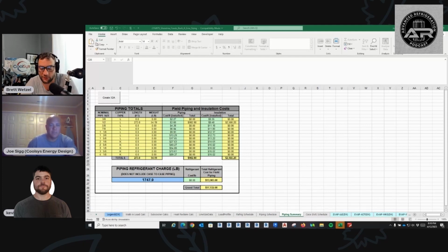All right, so one more time, you take the amount of case piping volume of refrigerant, that volume of CO2, and then you multiply that number by 1/4, because we're not using the flash tank as a full pump down device. We're only using it as an operational piece of equipment when the system is running. We may be able to pump one circuit down into it, but not the whole store.